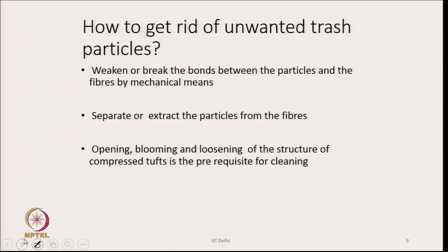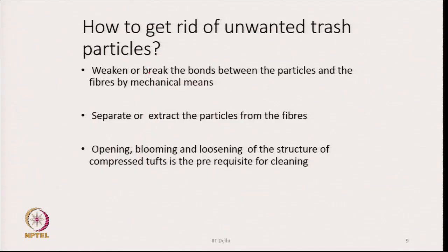Now, how to get rid of unwanted trash particles? What is the basic mechanism that we can follow? Weaken or break the bonds between the particles and the fibers by mechanical means. Somehow we have to weaken or break the bonds between the particles and the fibers, and this can be broken by mechanical means, that is, by applying mechanical energy.